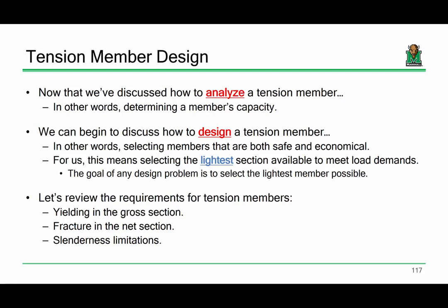But imagine that instead, as the structural engineer, I use maybe the same 5 shapes over and over and over again. Maybe some beams aren't as economically designed as others, but in the end, the whole system is economical. Does that make sense? It makes more sense in the long run that you might actually be sizing an element that's a little bigger than it needs to be, because in the big picture, that design makes sense.